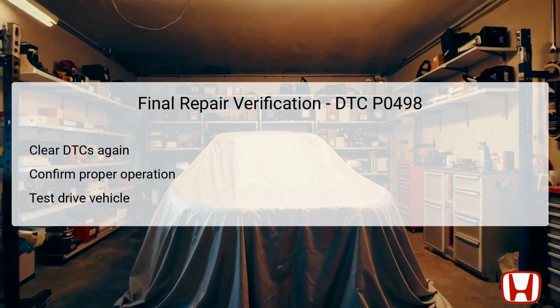repairs have been effective. Start by clearing the DTCs from the vehicle's memory using the HDS, and then recheck for any faults. Following that, it's critical to conduct a test drive under varied conditions to ensure that the EVAP system operates correctly and that the check engine light remains off.